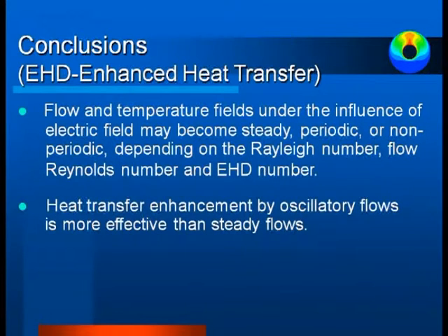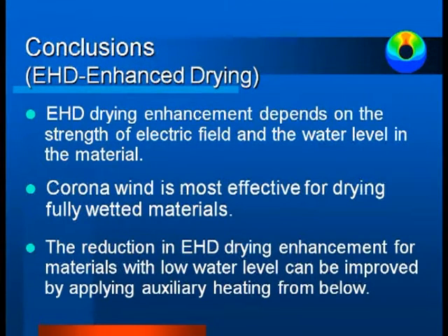What we are seeing today is that the flow and the temperature field under the influence of an electrical field can become steady, periodic, or non-periodic, depending on the Reynolds number. The heat transfer can be enhanced by this oscillatory flow. In terms of drying, the enhancement depends on the electrical field strength and the water level.